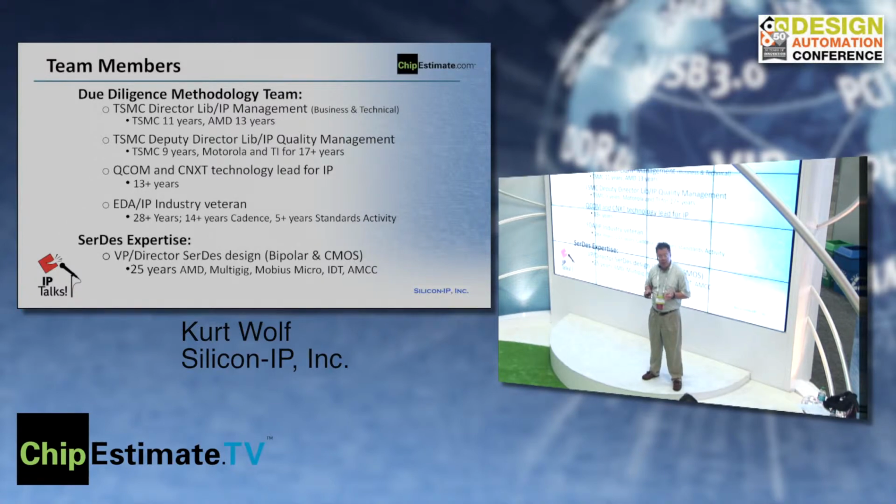If you think about what happens at a plug fest, it's set up in a hotel. There's a conference center, there's a table set up, and you're plugging devices into systems, but it's in this kind of controlled environment. That's not the real world. And so, fortunately for Johnson, what the chip guys find out is a lot of times the IP may pass a plug fest, but it doesn't actually pass the full datasheet conditions across process, voltage and temperature.